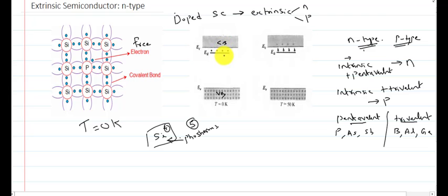And here one additional energy level is shown. This energy level indicates the impurity level, the amount of impurity concentration we added. That level is represented by ED, and it is also known as the donor level. So the impurity we added is known as donor impurity. Donor means an extra electron is generated. The donating state is known as donor. One electron is extra, so ED indicates the donor level.